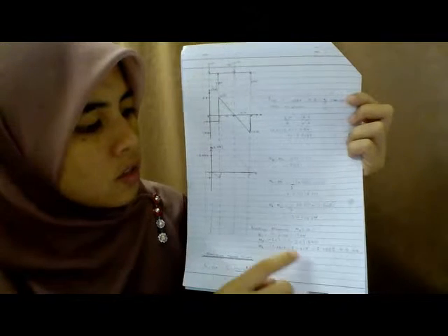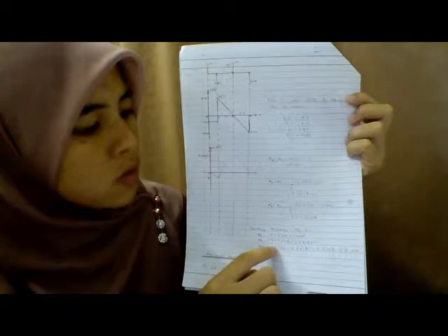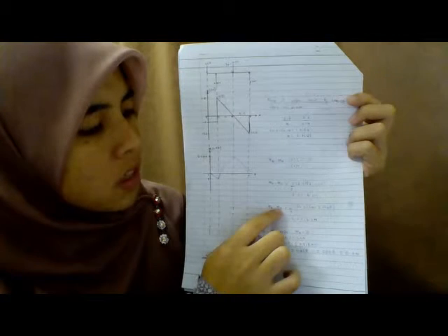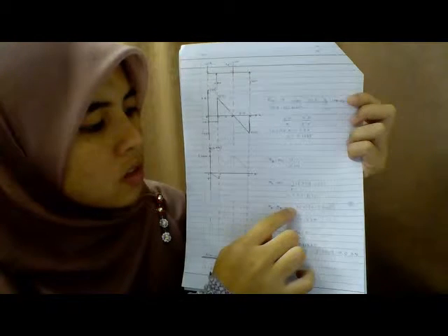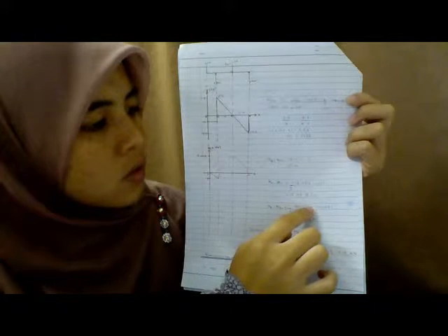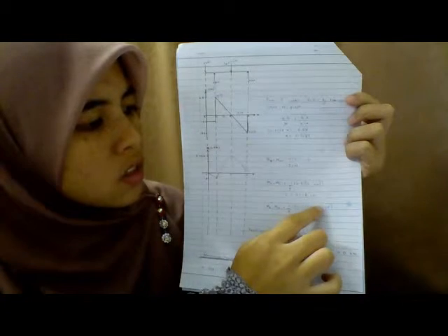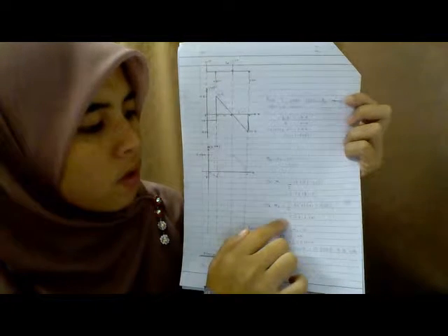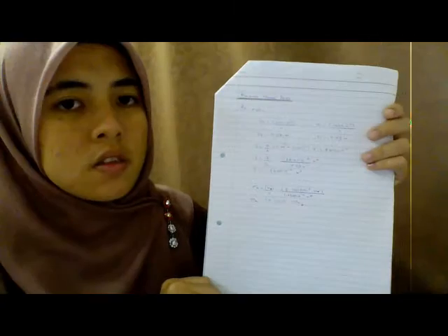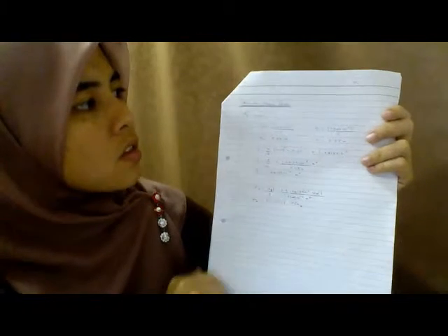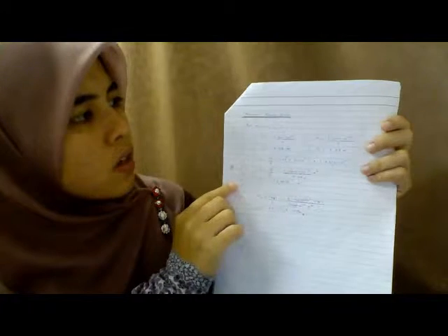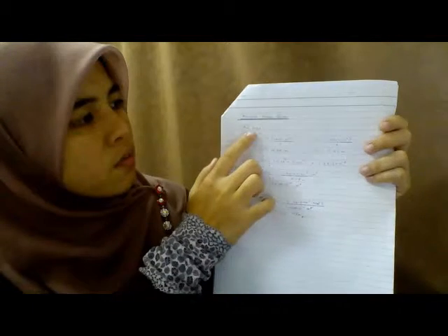And then this value, negative 5.0416, we can get it when the moment at B minus moment at D by using the formula of half times negative 5.55 times 4 minus 2.1667, and then we can get the value of negative 5.0413 kilonewton. So for the second question, we need to find the maximum normal stress. So we need to find the maximum normal stress for the pipe.